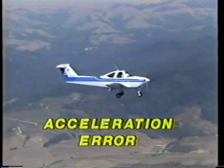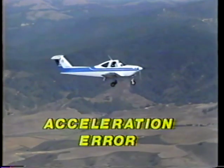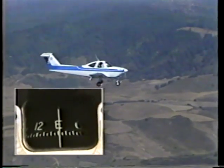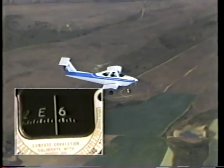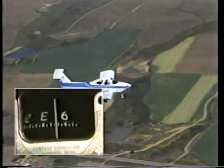The second dip error is called acceleration error. When on an east or west heading, acceleration will cause magnetic dip to create an indication of a turn to the north.